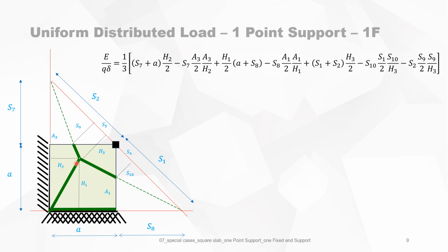So it will be this triangle, and this triangle. So everything is a sum of triangles. Of course, when you take, for instance, this triangle, you will take the total minus the portion outside the slab, but it still is a triangle. So everything is a summation of triangles. So it means that the mean deflection is delta over 3. So that's why this 1 over 3 is here.